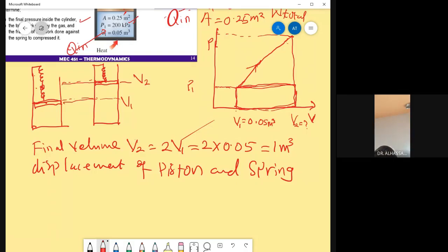When the piston is moving upwards, it travels through a certain distance. Let's say this distance is given by X. This distance corresponds to the change V2 minus V1. So delta V equals V2 minus V1. How do we determine this delta V? If I know this length, which is X, and if I know the surface area of this piston, which is A, then area times the height is going to give us the volume. So the volume of this region, that's what we are interested in.